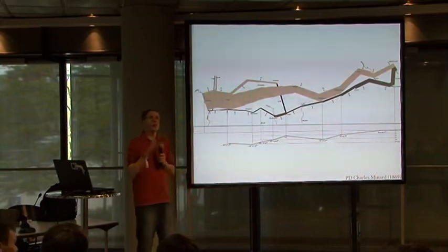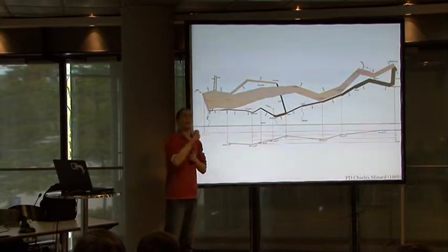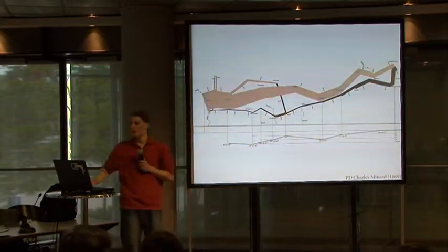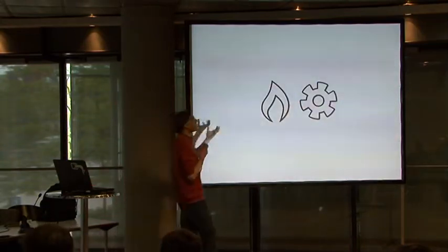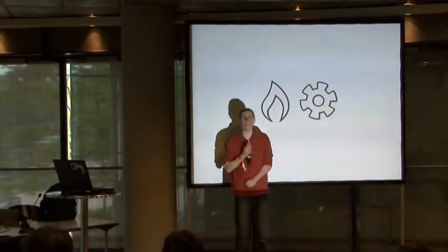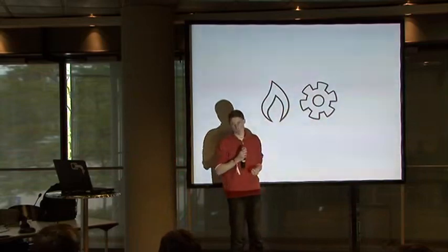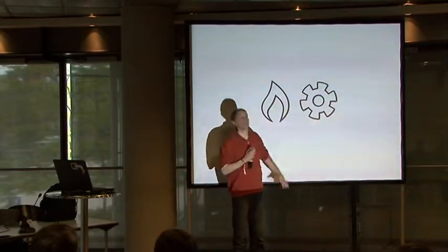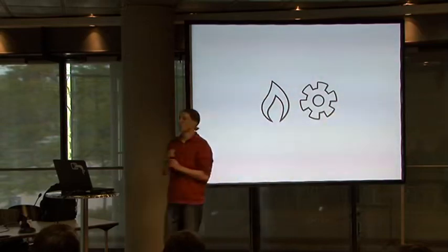But the point I'm trying to make is that this is a nice way of representing something where there's a loss that's avoidable, something that's not desirable. But for energy, it's not so. It happens that the transformation of heat into work is inherently, fundamentally, at a physical level, wasteful. It requires some energy to be wasted as low-grade heat, as low-temperature heat.